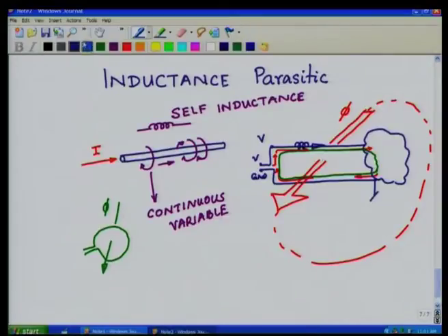It has dangerous consequences in the sense that if I am having another circuit here, unconnected with that, probably doing some other job, this flux, when it goes back, has to reach where it started, since all flux lines are closed paths. So, it will pass through a loop of another circuit, and it will induce a voltage there proportional to the value in this loop.